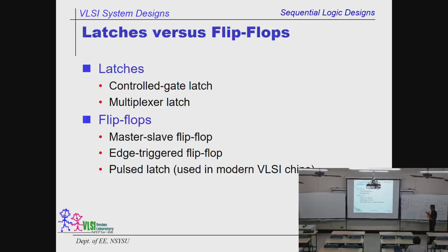There is a short period of time when the rising edge and the falling edge on both sides will overlap a little bit. That is what we are afraid of. So there is a very short window of time and a teeny tiny possibility that the D will be directly coupled to the D out. That is what we are worried about.